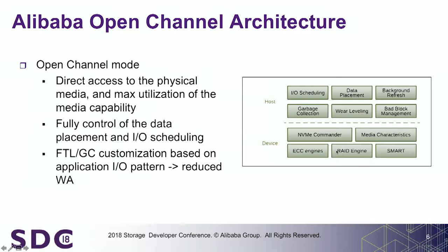Compared to traditional SSDs, which encapsulate everything in the device, here, as I said earlier, we move most of the FTL to the host side. In the device, we still keep the NVMe command handling, the media characteristics monitoring capability, and of course the ECC engine.